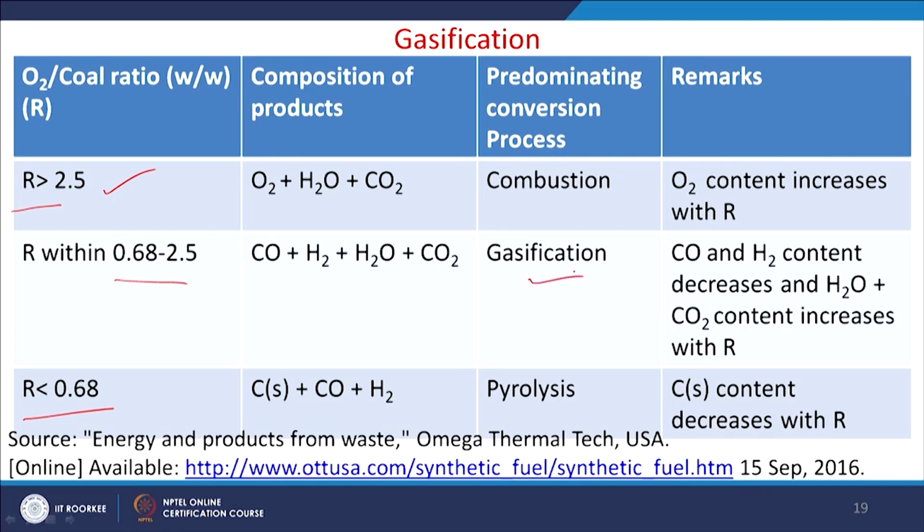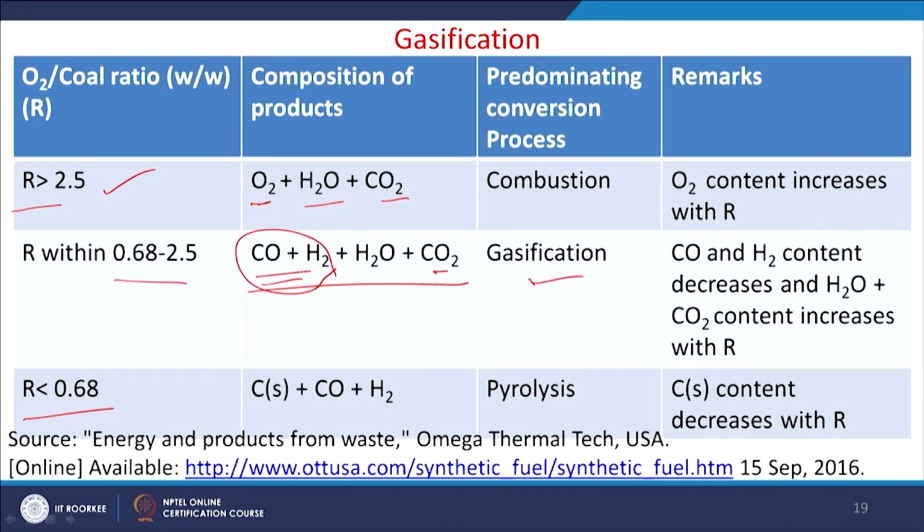So, if we use this gasification method, then what will we get? We will be getting CO and H2, but in case of combustion we are getting H2O and CO2, which is also available in gasification, plus oxygen. So, CO and H2 which we are getting here, so CO2 concentration will be less. So, carbon dioxide production in a gasification plant will be less, and we have CO plus H2 rich gas that can be used for the production of electricity as well as for the production of different types of chemicals. So, we will have an opportunity to capture carbon dioxide in situ in between, and also to make the syngas in a more economical way. I will discuss this in the next classes in more detail.